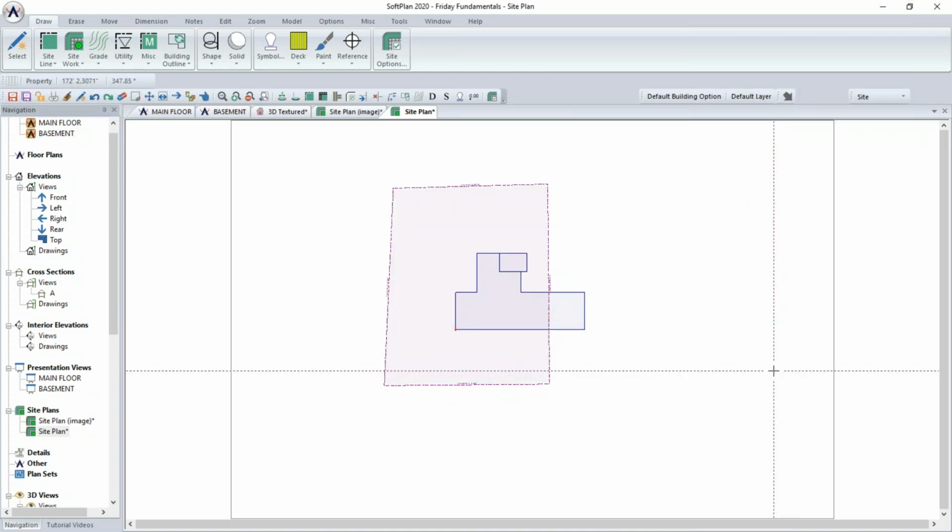And if the sight line has actually been done accurately, each property line will be precisely touching the endpoint of its neighbor. And if the last two touch, we get a polygon. And we know we have a polygon because we see the shading through it. If there is no shading, and that can happen as well, depending on the accuracy of the site information you have, you may need to do a little bit of work to clean that up.